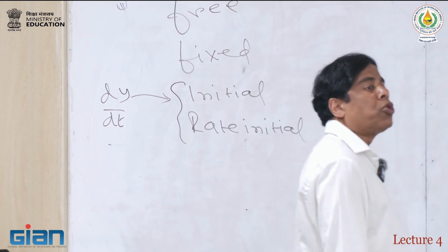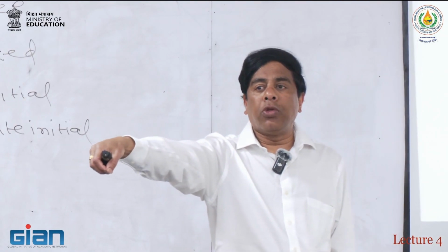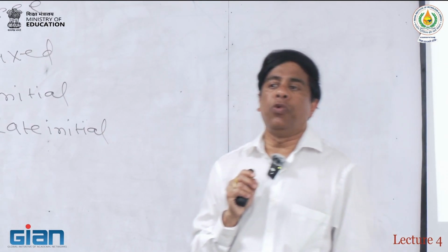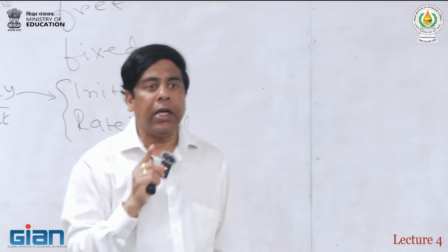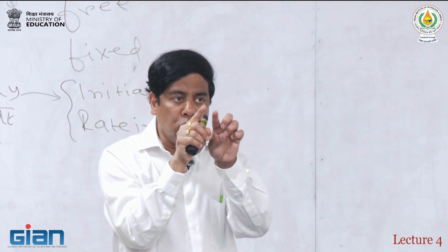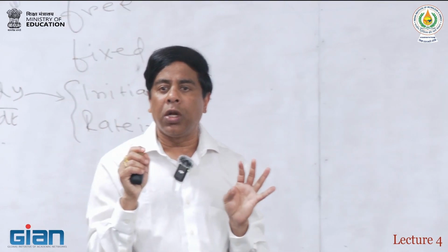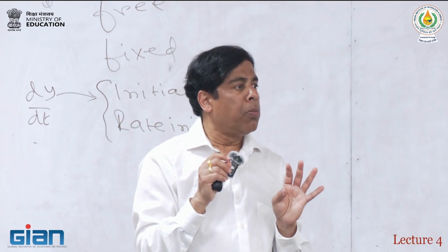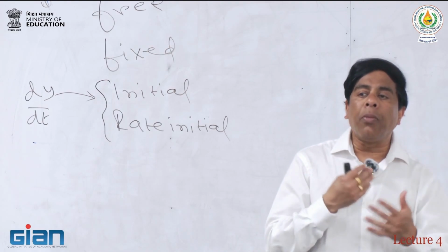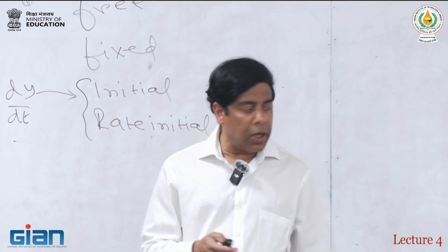This is a problem when you actually use software like Aspen Custom Modeler, because you drag and drop a block and you think it will work out. In Aspen Plus it does, because Aspen Plus does not let you specify any variables other than what you can. So for example, if you have 2 degrees of freedom, there are 2 variables that will be exposed to you. There is no way you can play with it to make it non-squared. But the custom modeler is not like that. It will give you a lot of options there. So in some ways it's a free tool, and you have to understand what you are doing. So that's what we wanted to be clear about here.